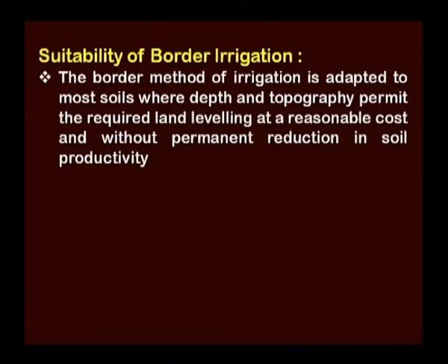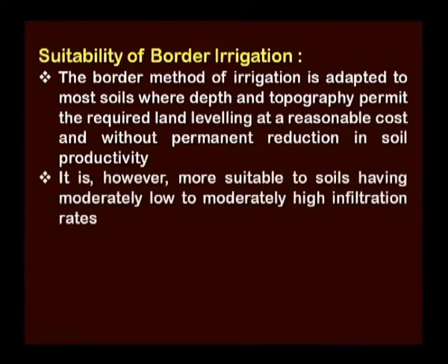Suitability of border irrigation. The border method of irrigation is adapted to most soils where depth and topography permit the required land leveling at a reasonable cost and without permanent reduction in soil productivity. It is, however, more suitable to soils having moderately low to moderately high infiltration rates.